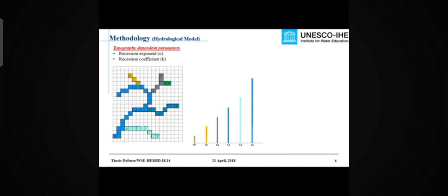After this, 2 additional parameters have to be defined. First one is NL, which is the total number of reaches, whereas the second is ZL, which is the sum of lengths of each individual reach. After this, these parameters are plotted on a logarithmic scale. We have already got the first point at the initial stage. Now, in order to get additional plotting points, we have to shrink these river reaches, and the shrinkage starts from the shortest one.